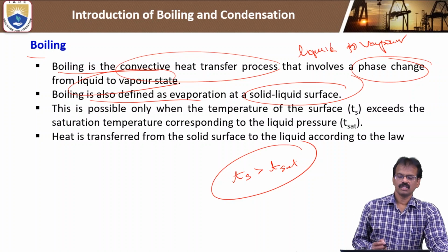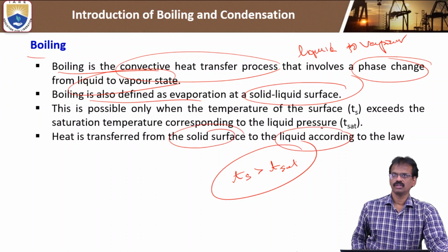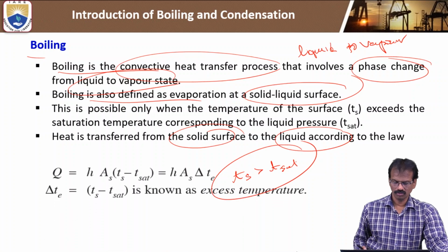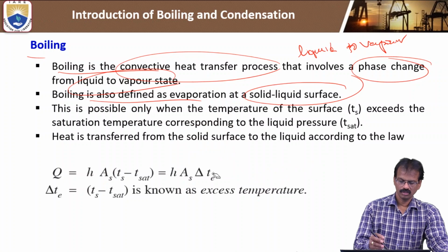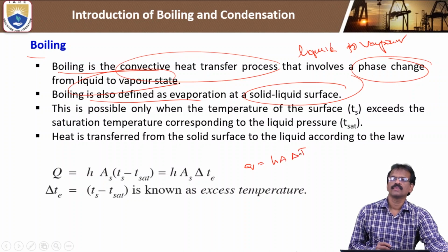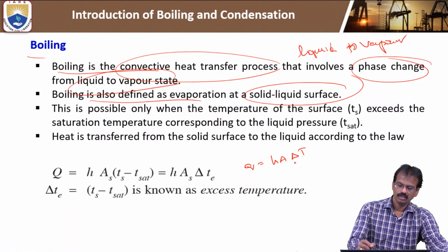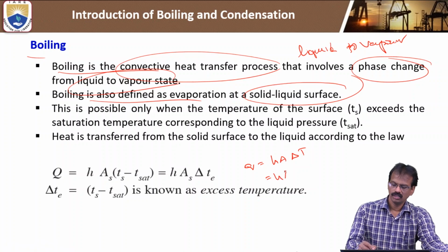So heat is transferred from the solid surface to the liquid according to the convection process. Q is equal to Newton's cooling law, h A delta T, where delta T is the temperature difference. Here A is the surface area, h is the heat transfer coefficient. We know this one.